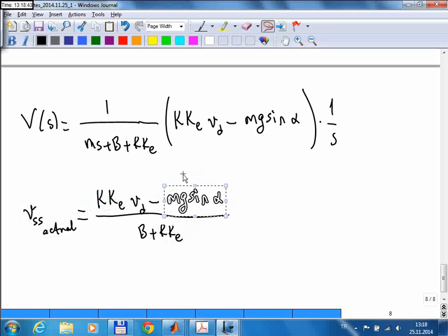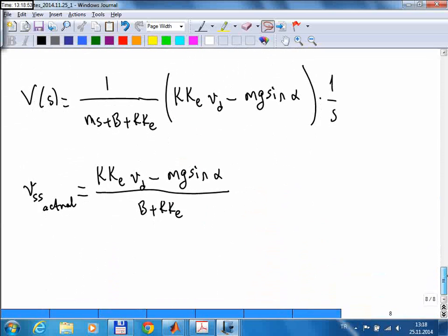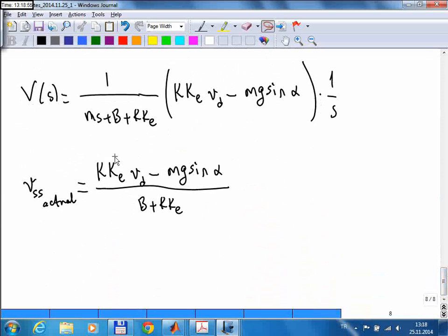And in fact, we will see that through simulation. So for example, in the open loop control, like 20% error in KE causes 20% error in the final speed. But in this case, depending on the value of k, 20% error here can cause an error of like less than 1% if you choose a proper k there.